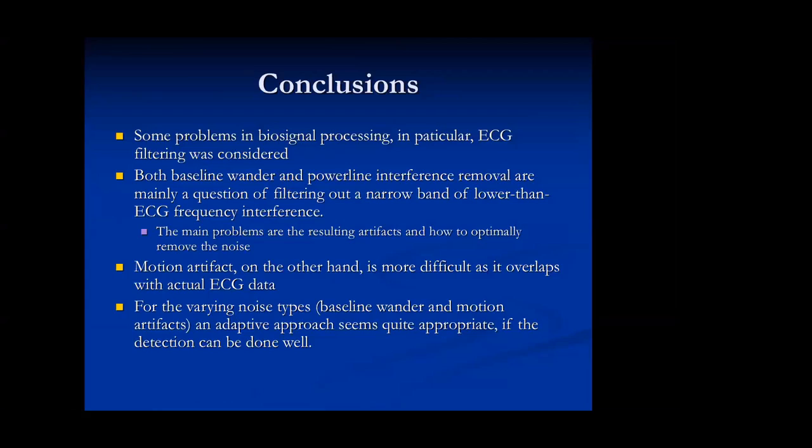So basically this is the conclusion. I started with the block diagram of the biomedical signal processing system. Before the A to D converter, we have some analog signal processing. I have discussed the various blocks. After that, digital signal processing: I have discussed basically the adaptive filters, singular spectrum analysis, and independent component analysis. These are the three different techniques we can use to efficiently remove the artifacts from the ECG and EEG signals.